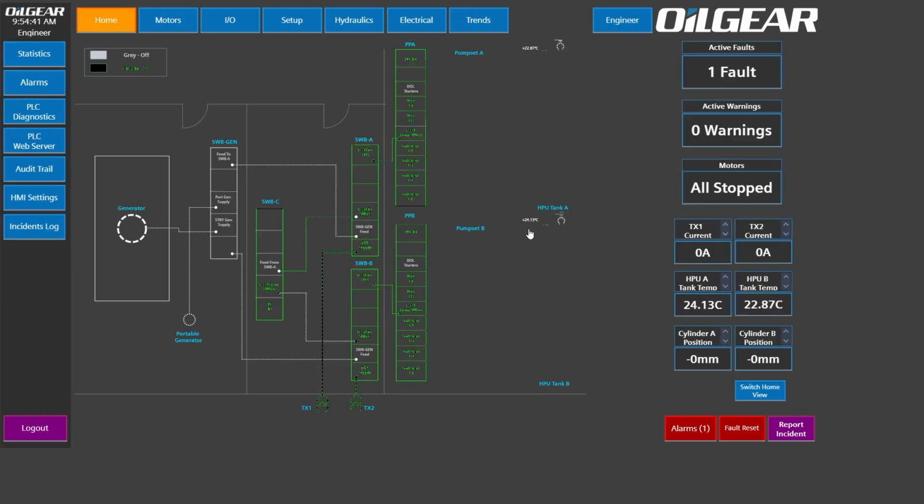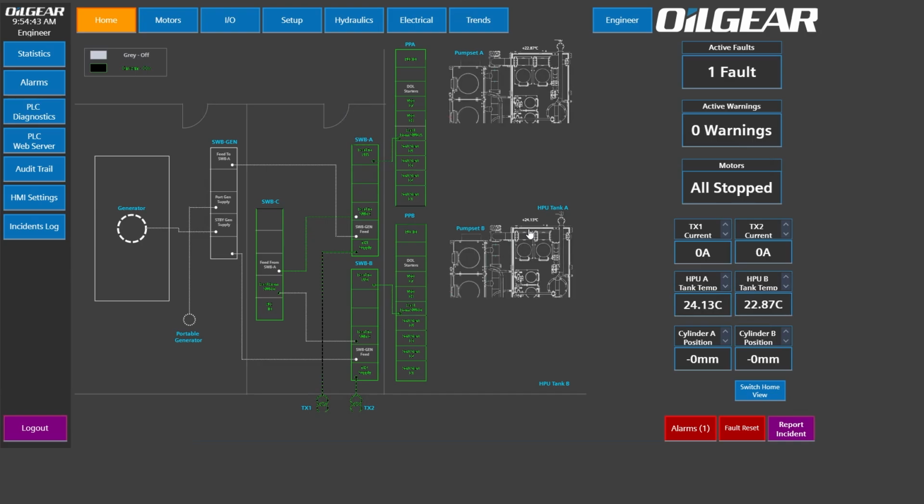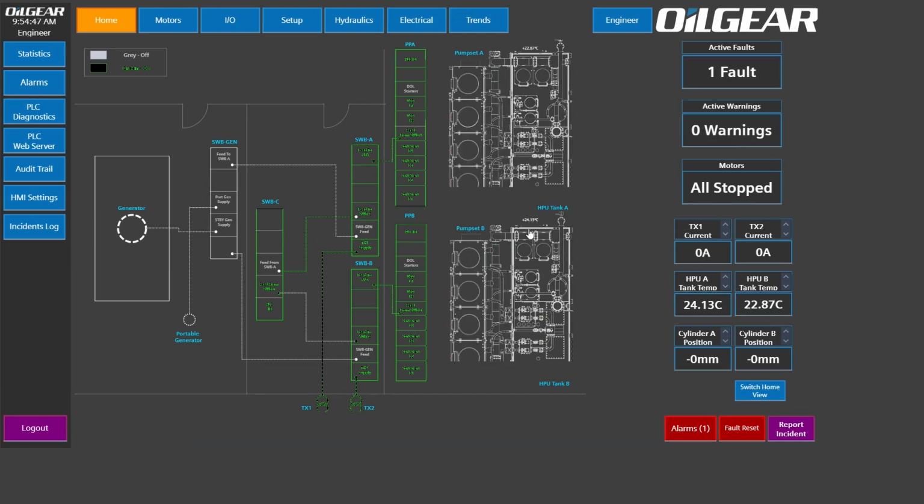I just thought that's a decent safety feature, and it would have been good if my company had implemented that years ago, because you've been able to read the clock time of the PLC forever, right? So let me know if there are any pitfalls to this. Obviously, if the operator knows about it, maybe they could change the time on the PLC. But again, the whole point is that you'll be done commissioning, and the operator will never know that that O button or R button or any of the other stuff existed.